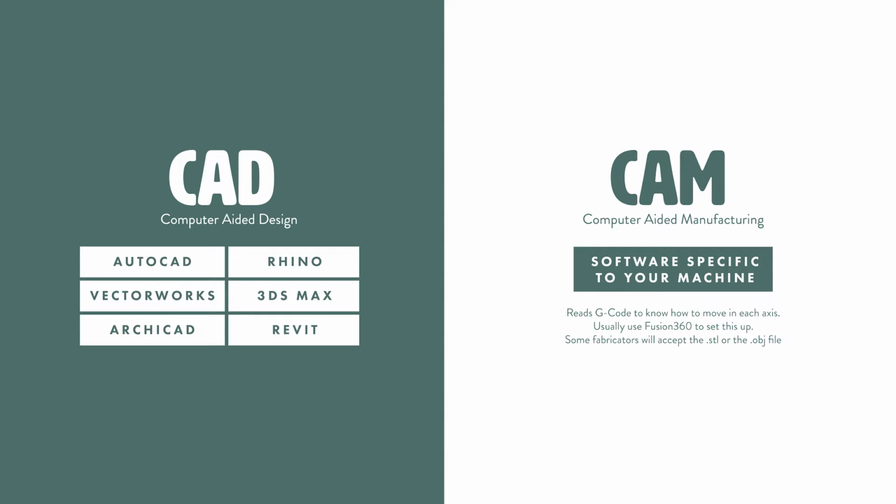Now, if we were controlling the entire workflow and we were operating the CNC mill ourselves, what we would need to do is actually create that G-code using a software like Fusion 360, where you design the entire process and workflow. You tell the machine what bits it needs to use, you say how big the bits are, how fast the machine is going to be spinning, all of the toolpaths all the way along.